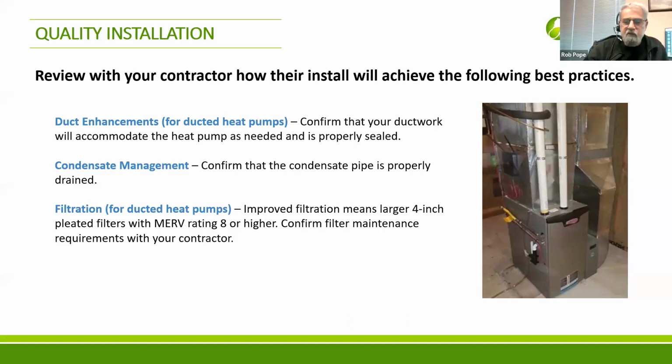Yeah, thanks for that. You've got to confirm that your ductwork will accommodate. We already talked about that. Condensate management: you have to plan those condensate lines. Sometimes in a ductless system you need a pump, if you don't have an adequate route using gravity to get rid of that condensation, so you're pumping it out. You just have to make sure that's all thought of and taken care of ahead of time.